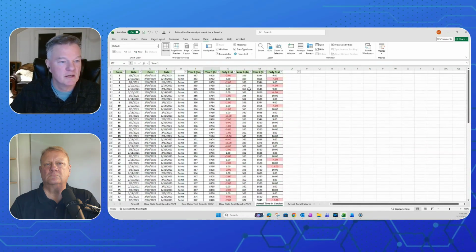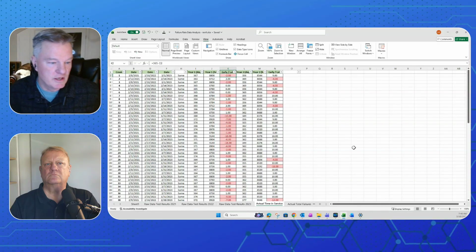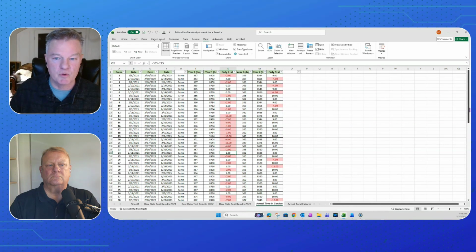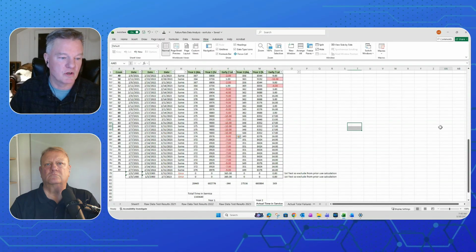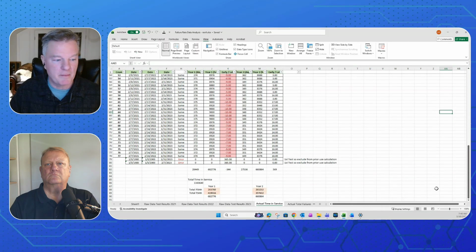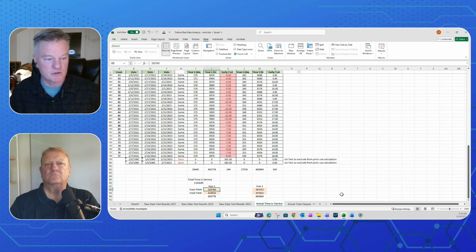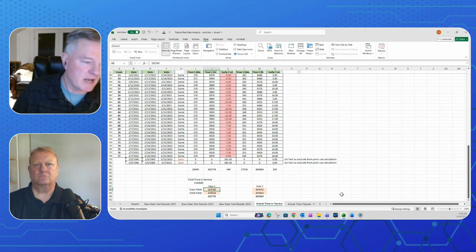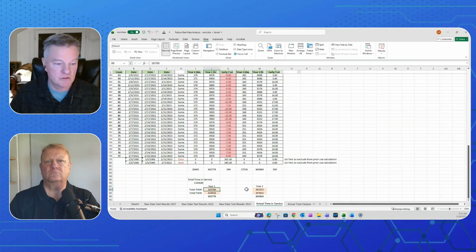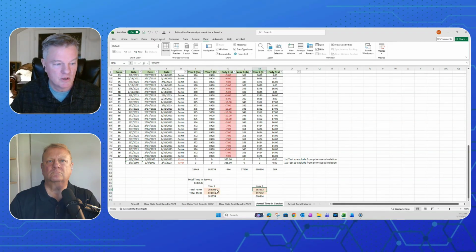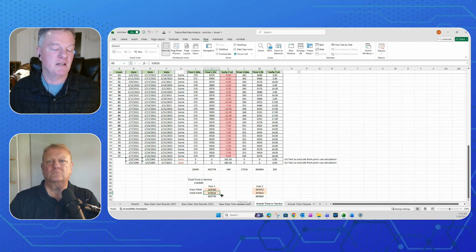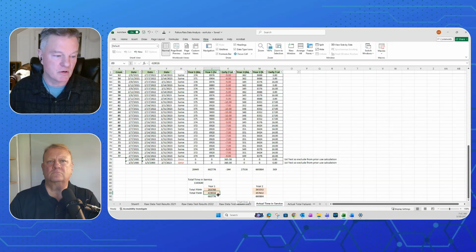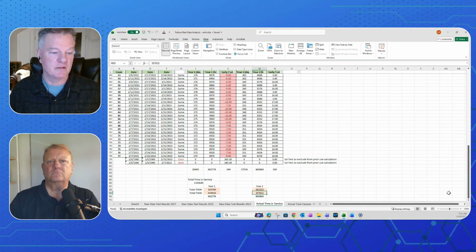And you can see that in some instances we tested 2 days early, some days we were 1 day early. They were doing pretty good on testing on time. There's a couple of things where they were 10 days early, no big deal. What ended up happening is in year one for pressure switches, I had 263,000 hours time in service. Year two, I had very similar numbers, 760 versus 232. Temperature switches, because they removed some, I had 419,000 hours time in service in year one versus 379.